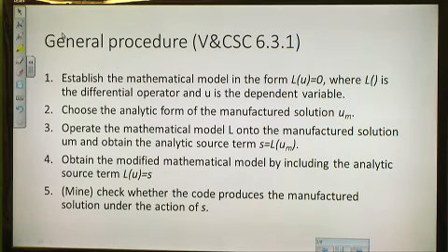Now, the reason that I hedged about step 2 is that one of the things that you can do, like when I compared two codes, I can take essentially the displacements that I get from one code and plug them in, and I say this is my manufactured solution, and see what kind of loading it generates on the other code, and compare the loading that I put on the original code to the loading that comes out from the second one. So there are variations that you can play.